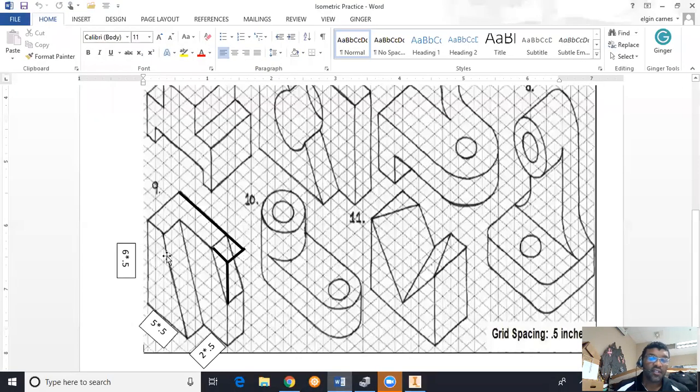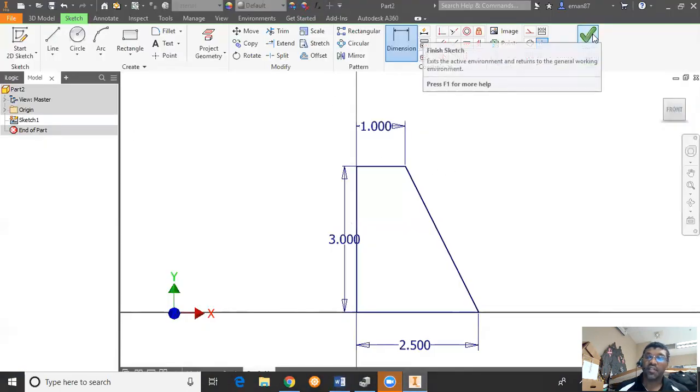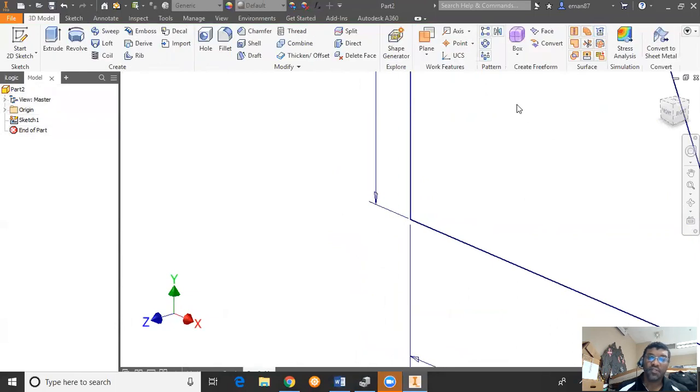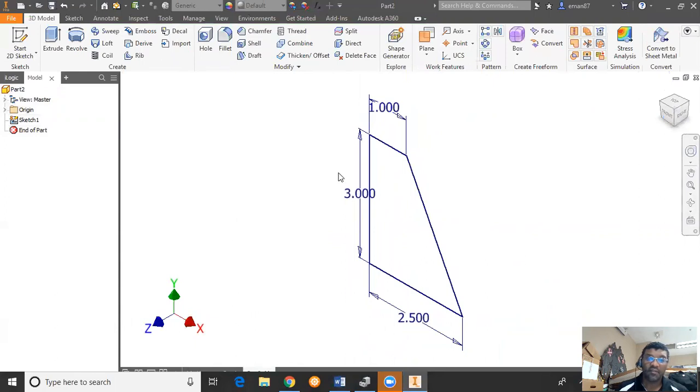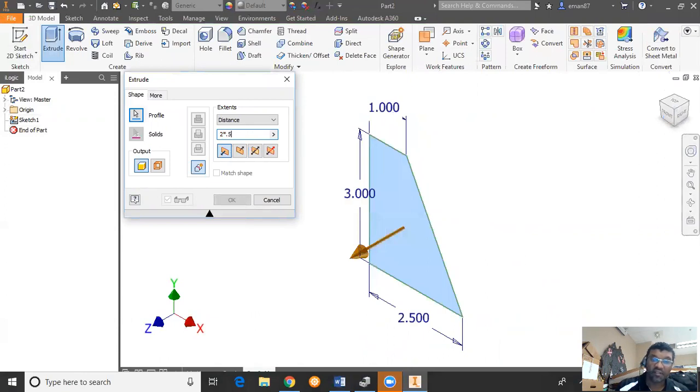So when I look at the drawing, there are no more lines to be drawn. Everything's been accounted for in the sketch. Now I'm going to give it the depth that it needs. I'm going to do an extrusion now. So to do an extrusion, I got to go over here to Finish Sketch. You see it zoom out of my view. I'm going to click on this little cube right here and zoom it back into view. And I'm going to go up here to Extrude. And if I have a closed surface, all should go well. Now I want to extrude. I just need to tell it how far I want it to extrude. So our formula was 2 times 0.5.